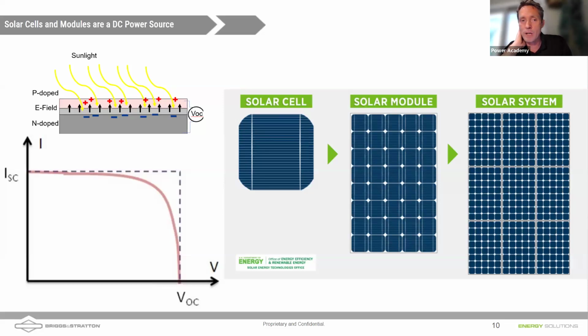I mentioned that the bifacial panels are not very beneficial if you're doing a roof mount array, right? You don't have much light on the backside of your panel, but for ground mount arrays, you can get 15 to 20% solar gains depending on what the background is. With grass, I think it's 10 to 15% additional power generated from a solar panel because of that reflected light that can come to the backside of the panel. So for ground mount arrays, that's important.